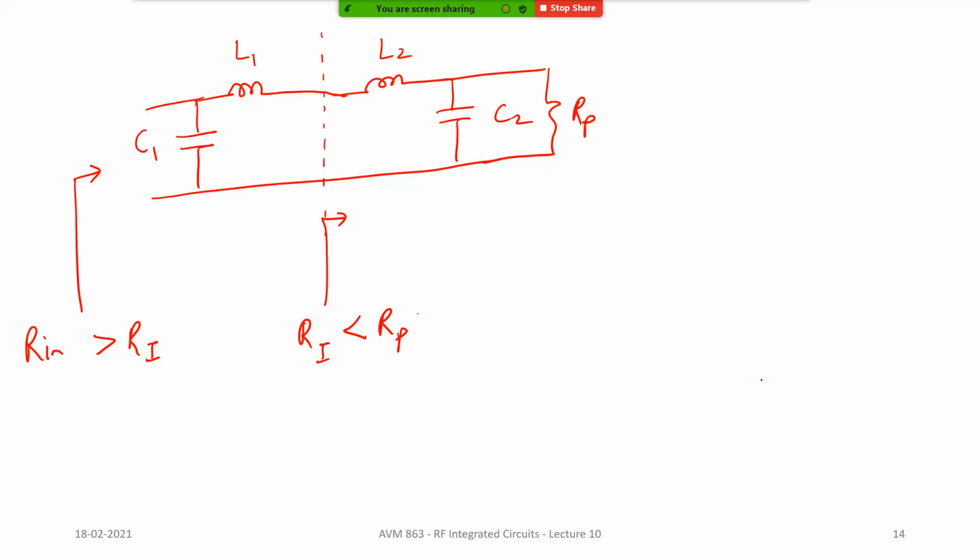So there is always a trade-off between opposing quantities, and in each design, you take an engineering decision and say, okay, this is the limit, I will live with this. Suppose your flicker noise is getting very critical for your particular design, you optimize it such that you have a little lesser flicker noise, but you live with a little more gate noise and other things.